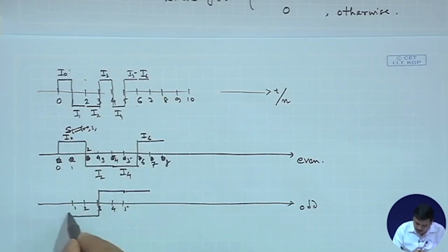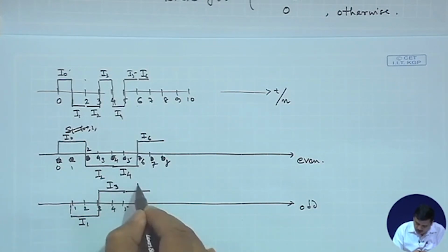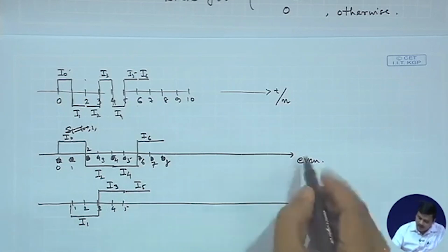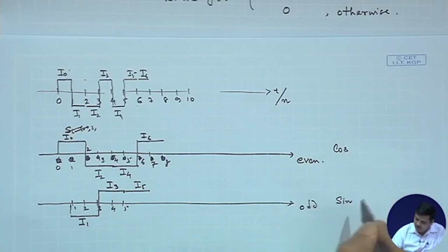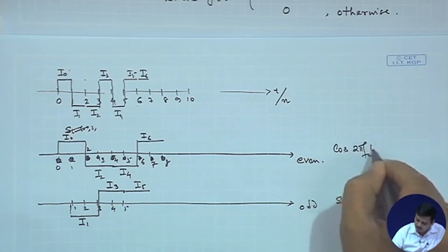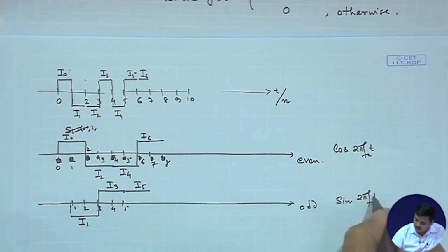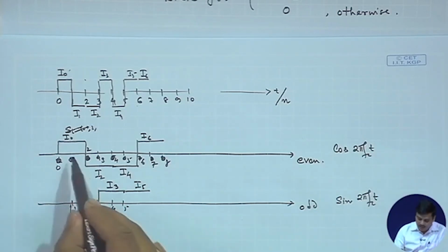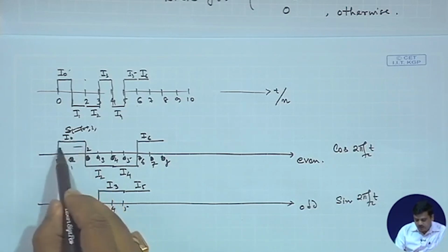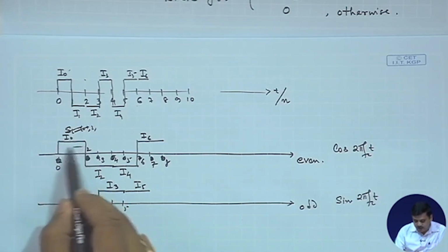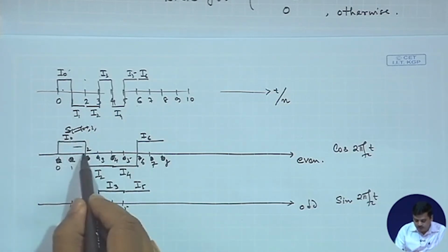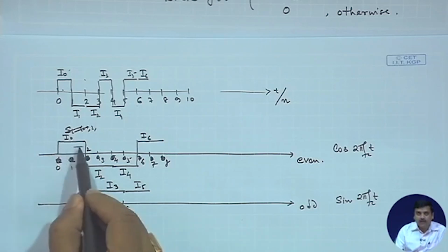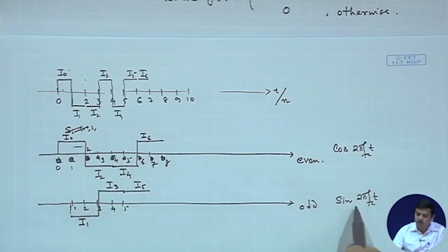So, here I get I 5. So, here what you see is this is I 1, this is I 3, this is I 5, and I would modulate a cosine with this and I would modulate a sine with this, right. So, if I am going to do this, in that case each of the symbol durations would become twice this period T, this also is twice, but in a 2T interval I am sending 2 I values overall, one along the I channel, one along the Q channel.